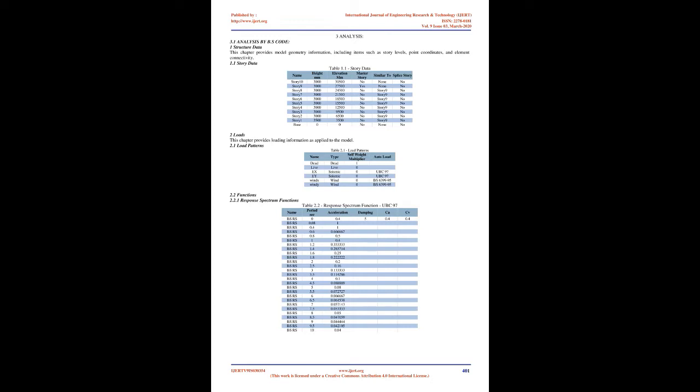1.2 Methodology. The methodology worked out to achieve the mentioned objectives is as follows. Point 1. Modeling of the selected building in ETABS software. Point 2. Retrieved time history and response spectrum of structure from the software. Point 3. 2 models as per the codes, i.e. Indian Code and British Code specification, were made. Point 4. Calculated push analysis, seismic forces and load combinations as per IS 1893-2002 and BS 8110-1997. Point 5. Analyzed the models and the data is presented to evaluate stability.